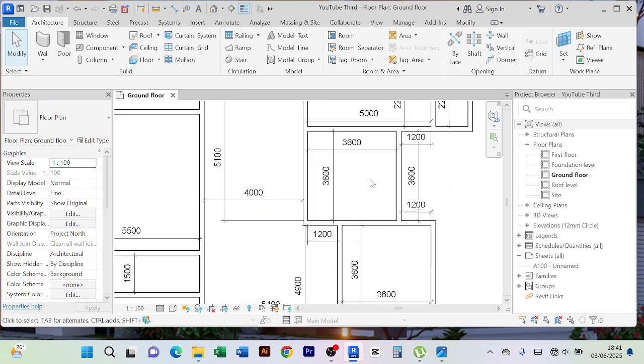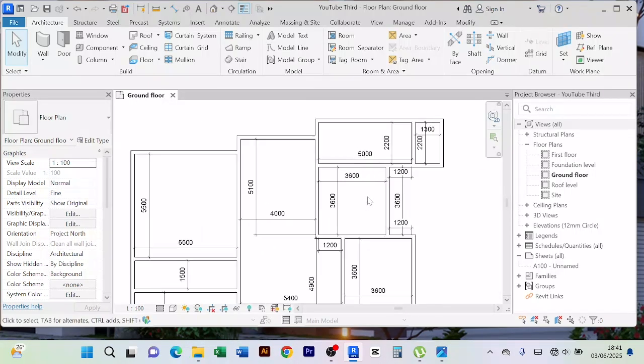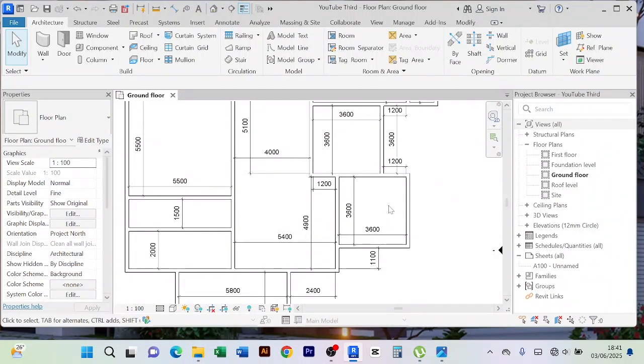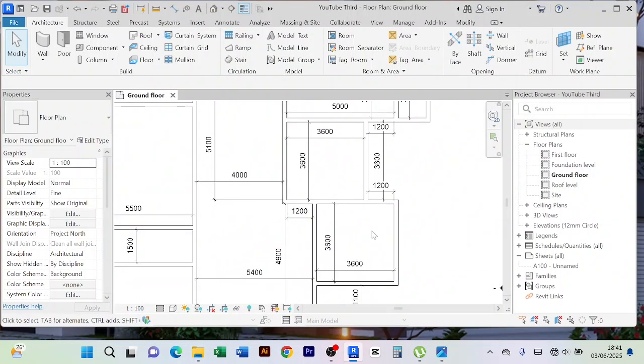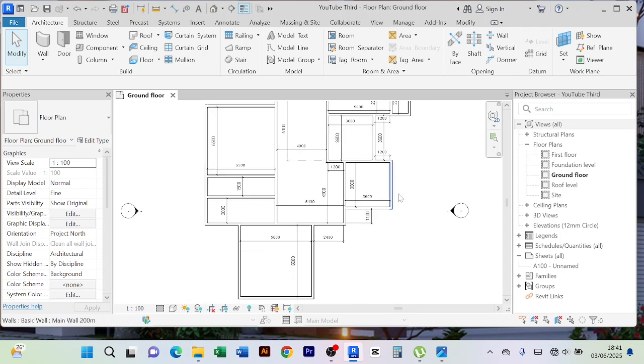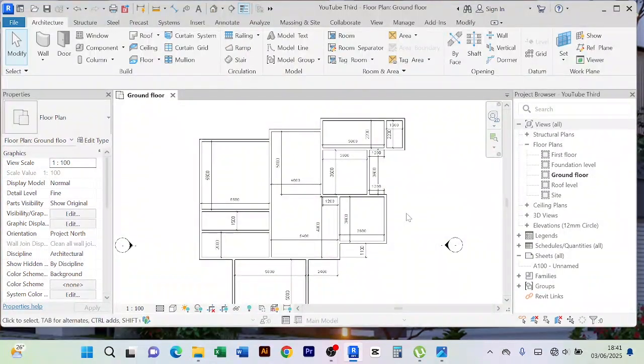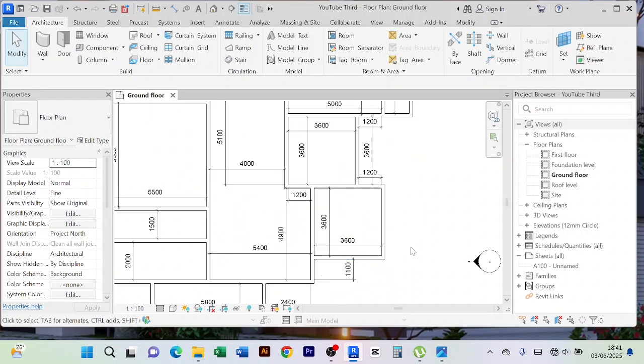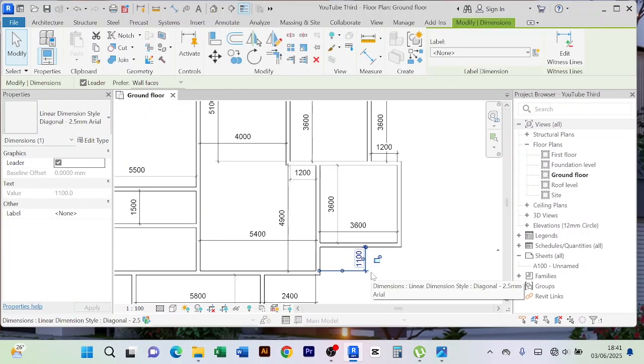If you don't furnish your rooms, you might think the space is enough, but at the end of the day, things may not work. It may not be functional. So it's very important for you to always ensure that after creating your floor plan, you furnish your rooms. And it is also important to first sketch this floor plan somewhere, especially in your notebook, before coming to the software, because when you come to the software without any floor plans, you will struggle to create any meaningful design.